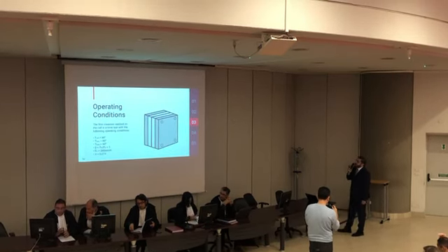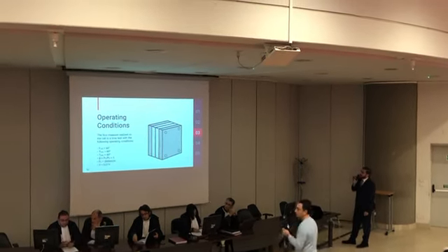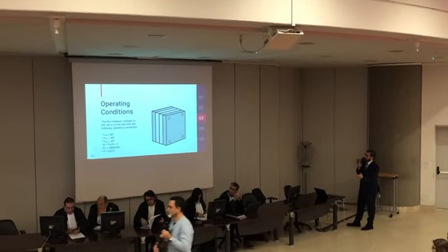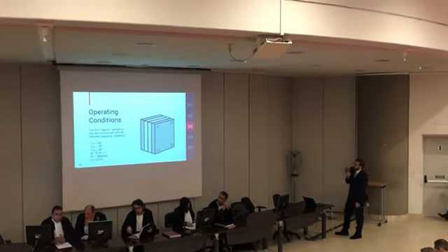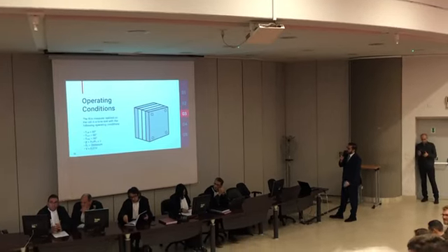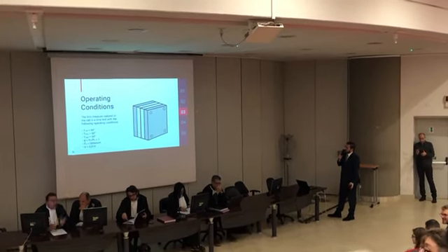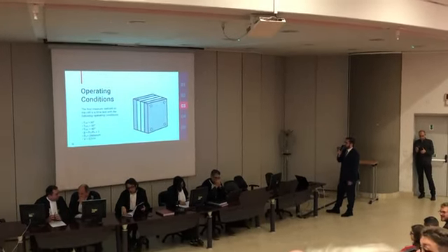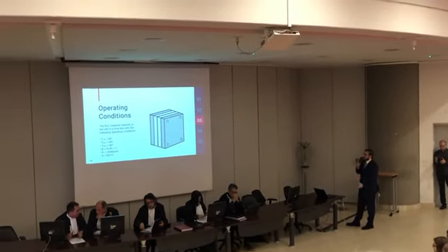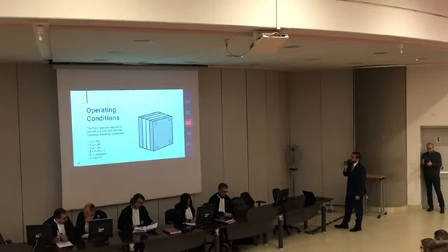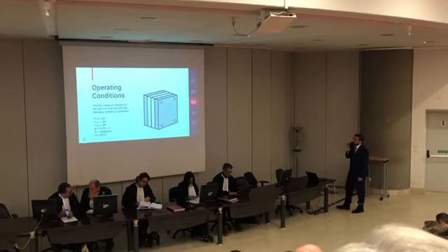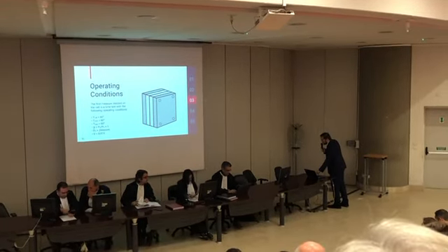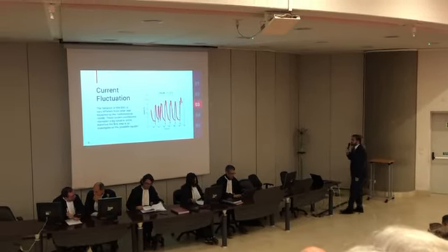The operating conditions for the first time test are the following: the temperature of the cell and humidifier is 60 degrees, the beta parameter, which is the ratio between the cathode pressure and the anode pressure, is 1, the flux at the anode is 260 SCCM, and the voltage imposed for the time test is 0.01.